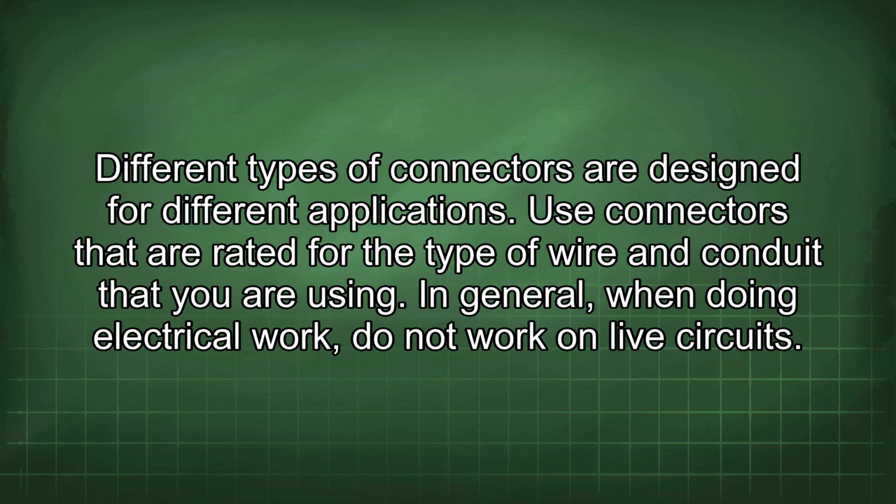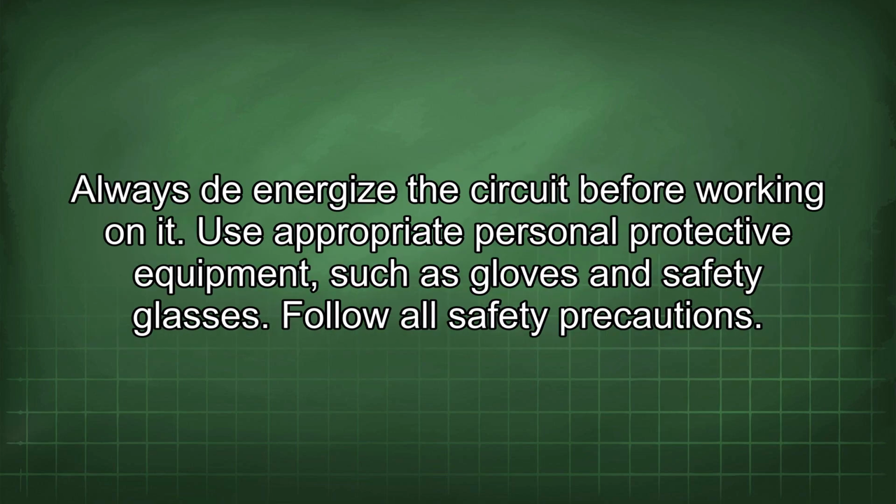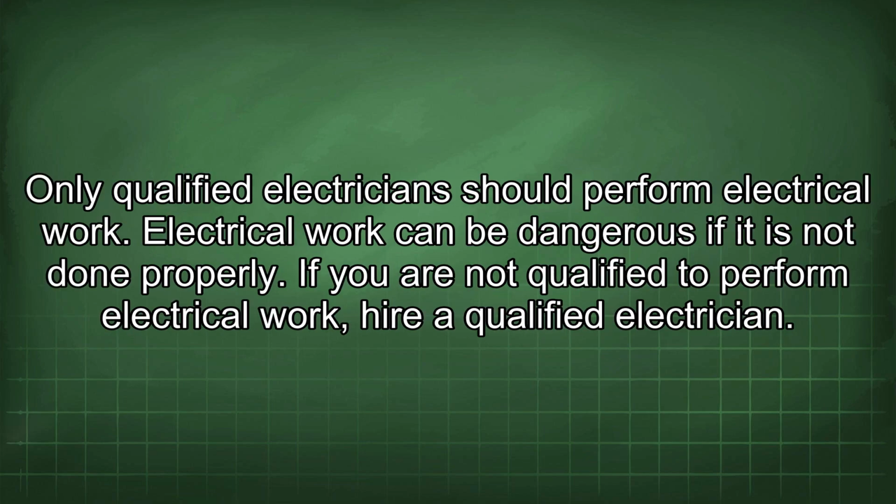In general, when doing electrical work, do not work on live circuits. Always de-energize the circuit before working on it. Use appropriate personal protective equipment, such as gloves and safety glasses. Follow all safety precautions. Only qualified electricians should perform electrical work.